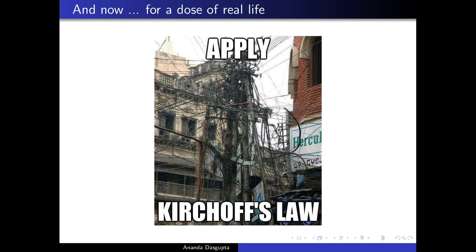So we will next describe a method by which this can be simplified a lot. And that is called Maxwell's method. It's known either as the mesh method or the loop method depending on which book you are reading. But the idea is the same. You essentially break up your circuit into loops and assign things called loop currents, which somehow magically take care, okay, not really magically, but they take care of Kirchhoff's current law automatically, and you only have Kirchhoff's voltage laws to be used.